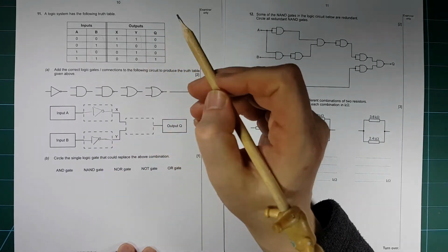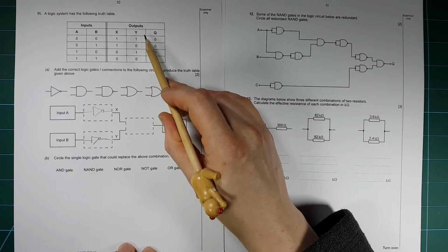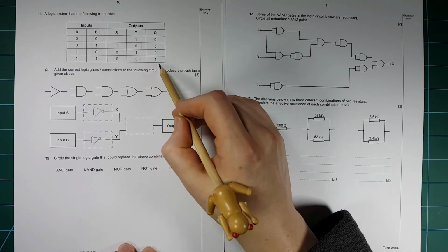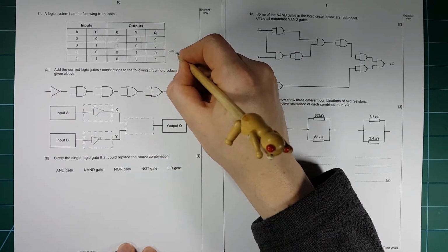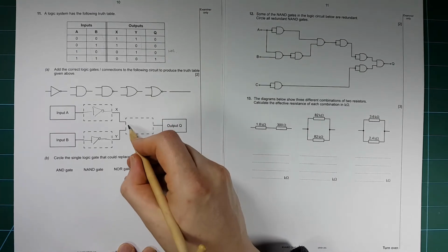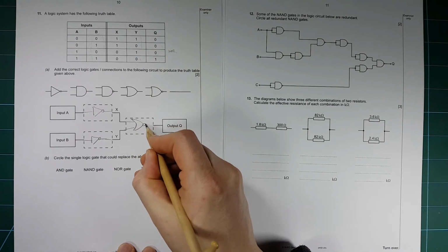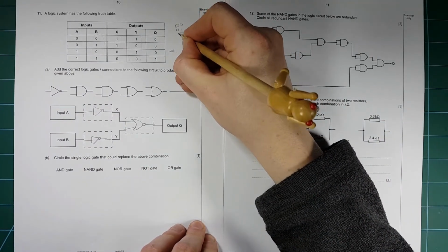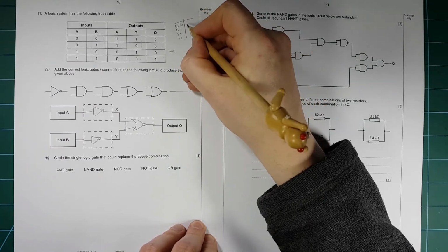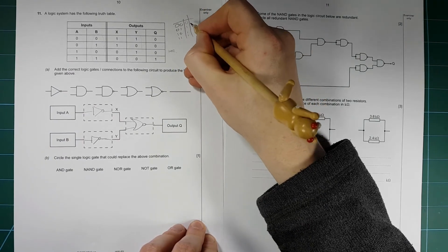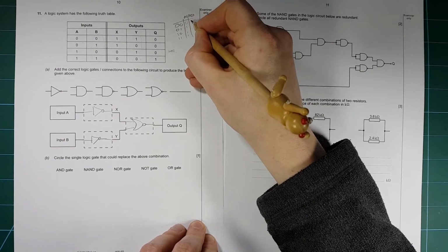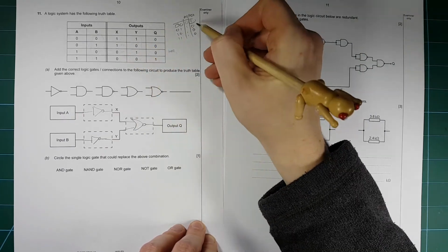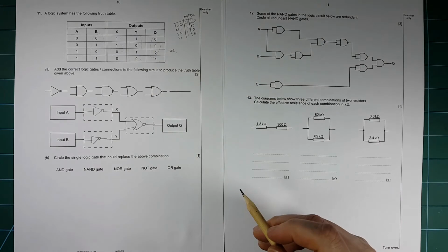Now we need to compare these two to get to here, and that is only when they're both 0. Is it a 1? So that is a NOR gate. So we want this one here, like so. Let's just check that. So 0, 0, 0, 1, 1, 0, 1, 1. So an OR gate would be 0, 1, 1, 1, and a NOR gate, that's an OR gate inverted, would be 1, 0, 0, 0. So when they're both 0, we get a 1, and any other combination, we get a 0. So yes, it's a NOR gate.